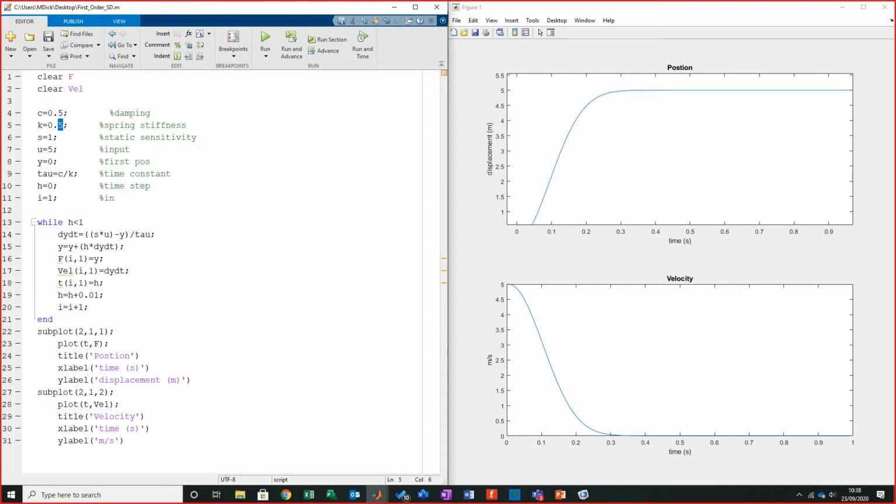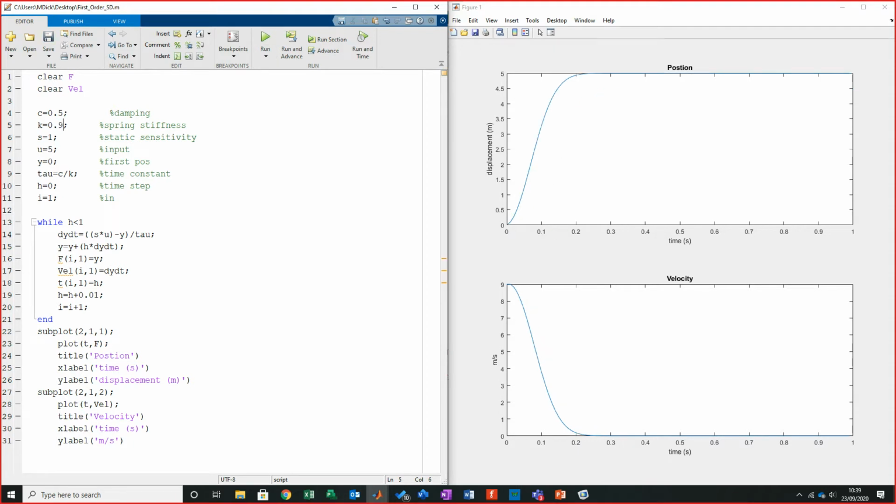But if we go back to the spring stiffness and then start to incur a greater spring, obviously what you're going to get is the spring's ability will slam shut. Based on that spring stiffness and our input, you're going to get that overall displacement, because I've given an initial input. However, the way that the spring responds, based on the strength it's getting, can become quicker, because I'm just encouraging a greater strength. So again, if you just run it, it will go massively out of control. And as a bit of kit, using something like this is really useful, because it allows you to tune for something simple like a first order system in this way.